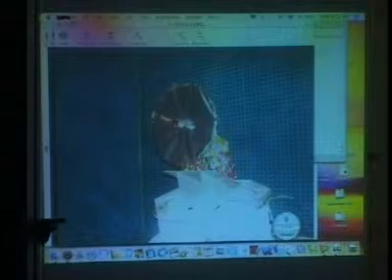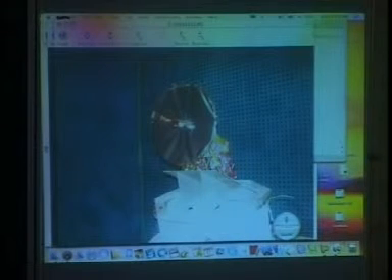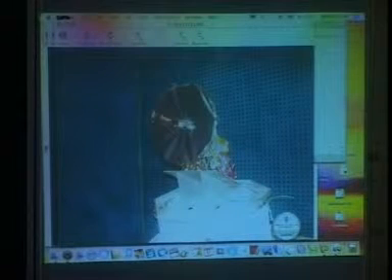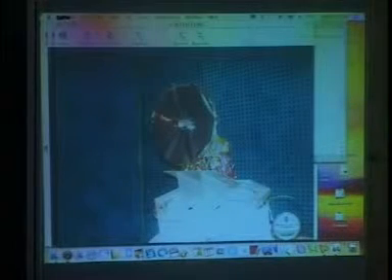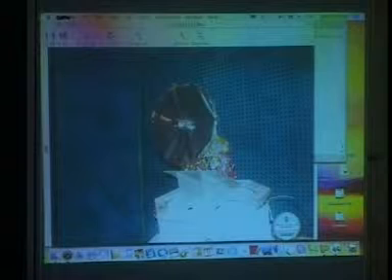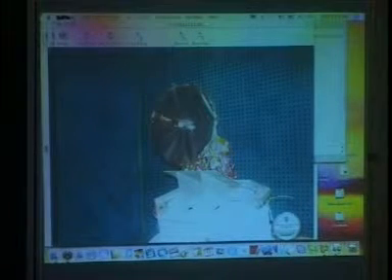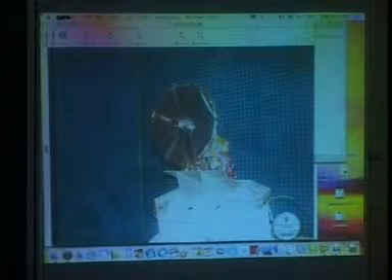See this one, this is another view of the same thing. You can see how many thermal design aspects you have to take care of. See here, you saw that the back side covers are all called MLI covers. There is a multi-layer insulation cover. Multi-layer insulations are used to make sure the temperature of the antenna is maintained within the specific range.